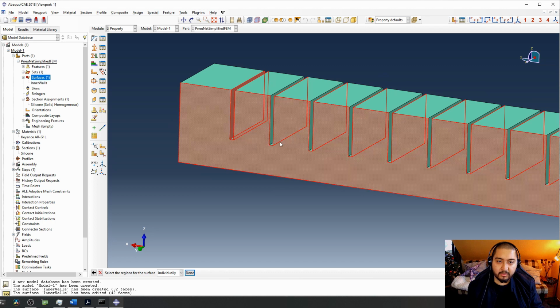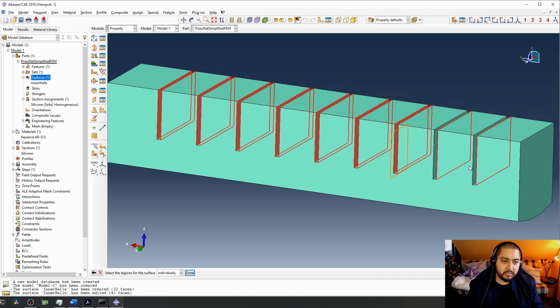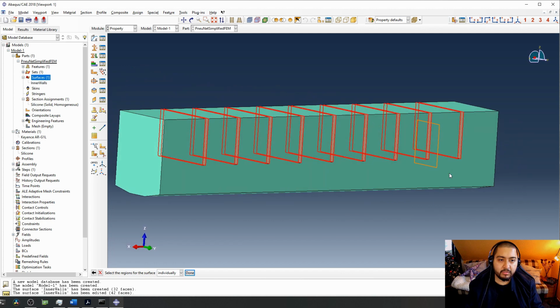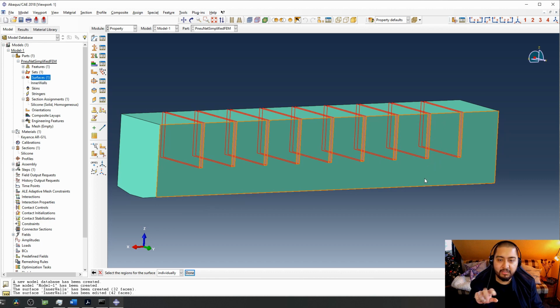To rotate that smoothly, and if you select one wrong, you just need to press the control key and then normal left click, and it deselects. And to rotate so smoothly, I use a 3D mouse from 3D Connexion. With mouse and keyboard, it's not more difficult actually if you have experience with the keyboards, but maybe you can lose one surface or something with the shift, control, alt to rotate in Abaqus.